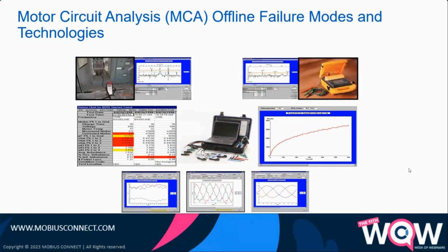Motor circuit analysis is also a very, very capable technology for identifying defects in electrical circuits and motors. There are two tests normally performed. That's offline motor circuit analysis, and then online, right? On the offline detection capability, we see its capability across many defects. Next slide, please.